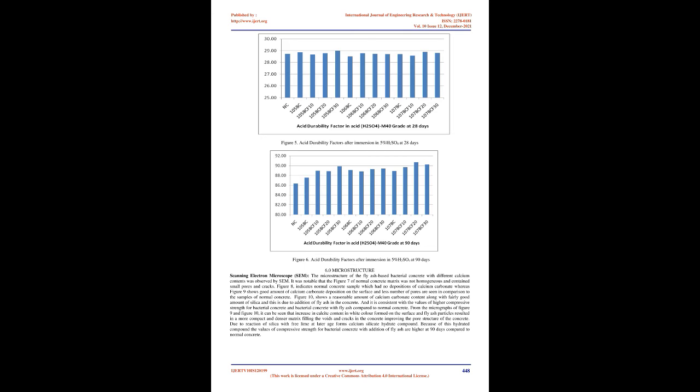4.3 Durability, acid test. The chemical resistance of the concretes was studied through chemical attack by immersing concrete blocks in an acid solution. After a 28 day period of curing, the specimens were removed from the curing tank and their surfaces were cleaned with a soft nylon brush to remove weak reaction products and loose materials from the specimen. The initial weights were measured and the specimens were identified with numbers.